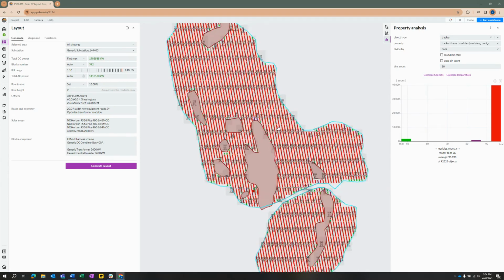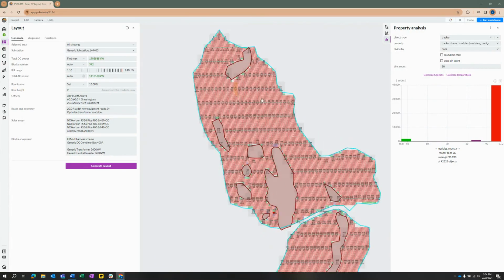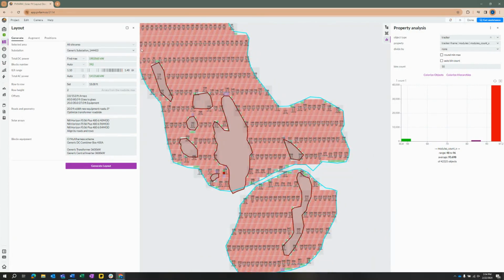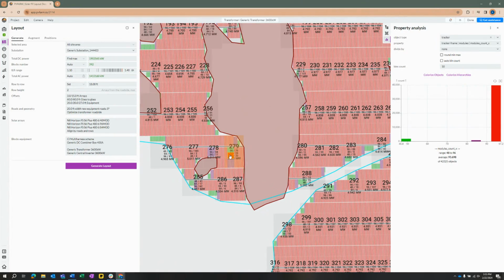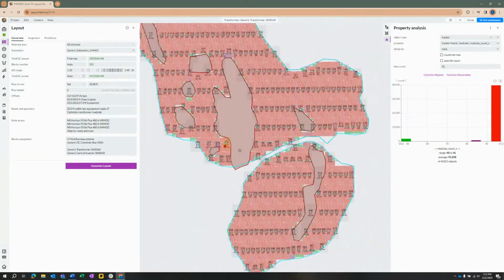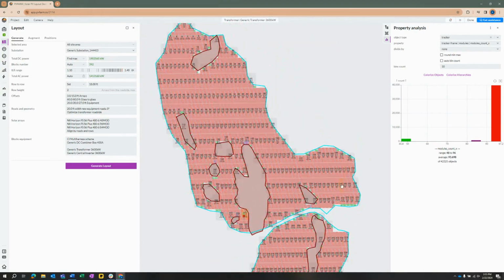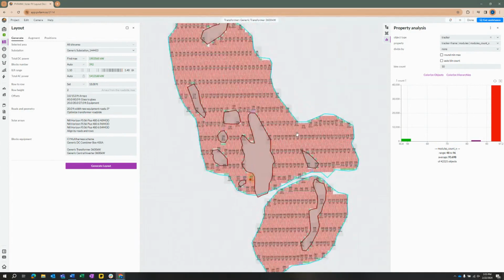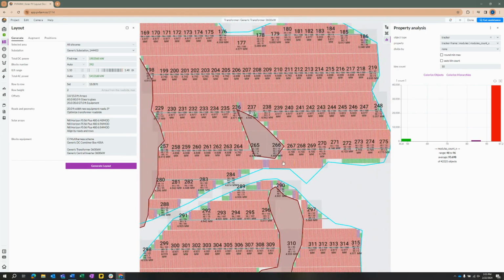So I think we can pretty safely say that we're going to go with the 48s, the 84s, and the 96s. Now, this is definitely something that you can play around with and try all different configurations. And this is a large site. Obviously, we're dealing with almost 2 gigawatts of power. So what we could do, like I showed you before, is duplicate this substation and have one substation for this boundary and one for this boundary, because what works best for this one might not necessarily work best for this one. But I want to keep all of it together so that we can really see the power of PV Farm and that it can handle these large scale systems. I think for our purposes, this is going to work the best.